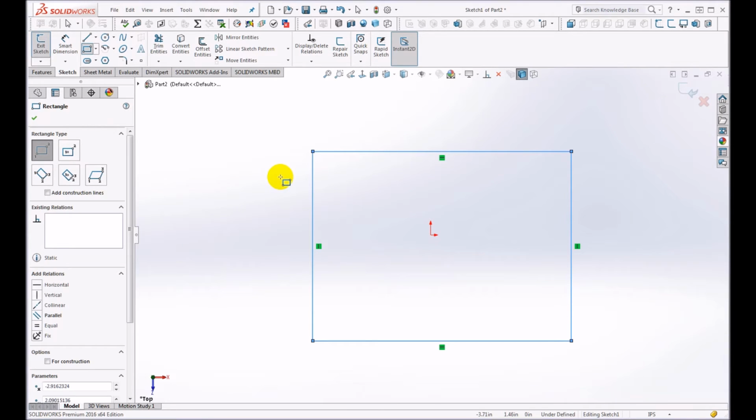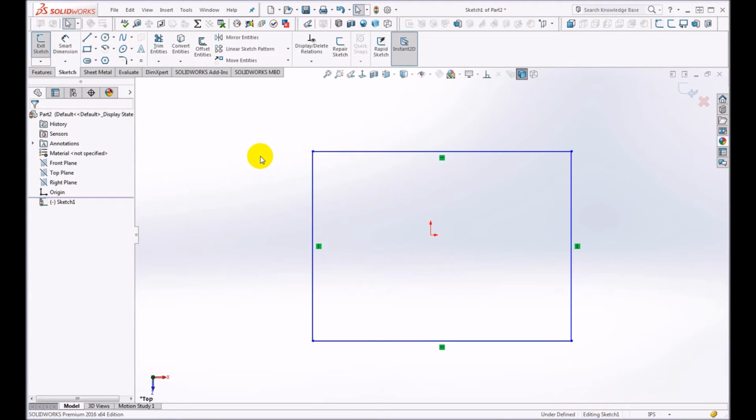In general, I use the Escape key. That's just a personal preference. So I will push Escape right now, and I've finished drawing a rectangle. It's not dimensioned yet. Dimension means that I take a particular feature, an edge, or a distance between two features, and I apply a numeric value to it, usually inches, but it could be millimeters or other units. I'm assuming that you're working in inches. If you're not, you should, again, stop now, make sure the configuration is set for inches, and re-enter this video.